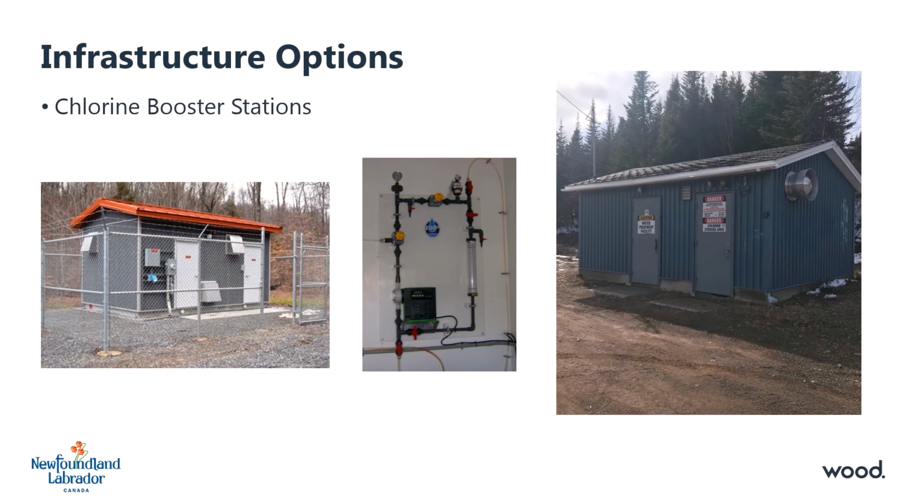line. Installing a chlorine booster station is the most expensive option we've covered here today, as it involves constructing an additional chlorination building with all the necessary chlorine dosing equipment. It would also need to be monitored just like the first chlorine dosing system, increasing the workload for the water system operator. I hope you have found the information we went over today useful for the operation of your community's